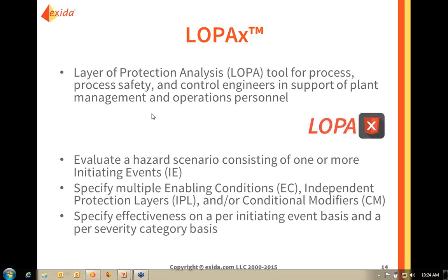Yeah, and here's a clarification on that question: 100% rated to prevent the hazard consequence. Since they have the same physical environment and are in contact with the same process, I may be inclined to consider a little common cause there, just to be on the safe side, instead of saying they're absolutely 100% independent, simply because of the similar design and environment.